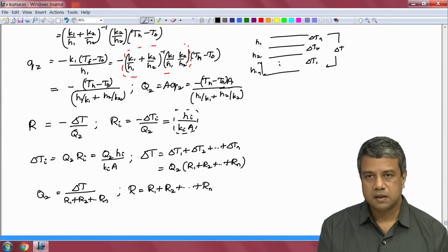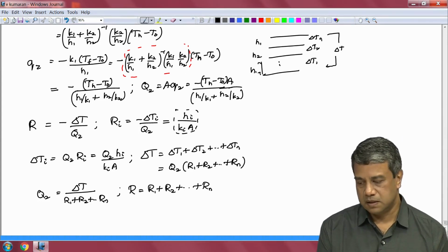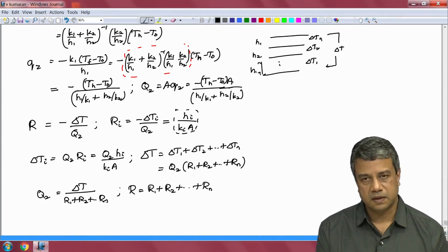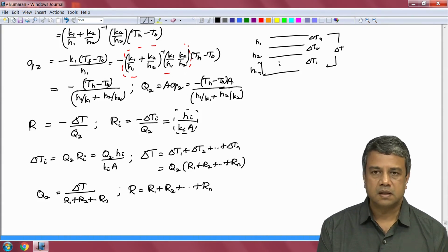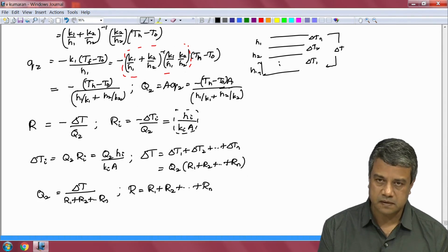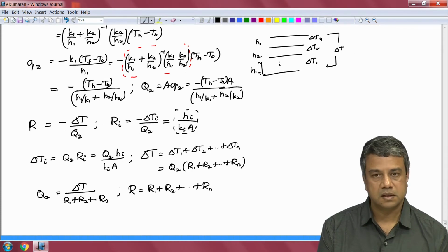Okay. So, this is for a case where there is no source and it is a steady state, and therefore, the temperature, or in general the field variable, in more complicated problems of mass or momentum transfer as well, the second derivative has to be 0. So, the field variable has to be a linear function, if the diffusion coefficient is a constant, with no sources and no time variation. The field variable satisfies a second order differential equation, d square field variable by dz square equal to 0.